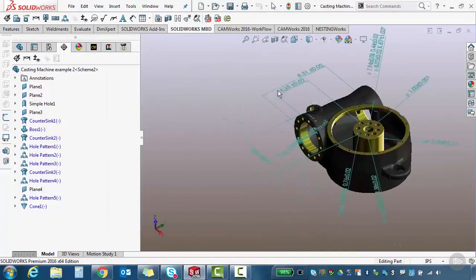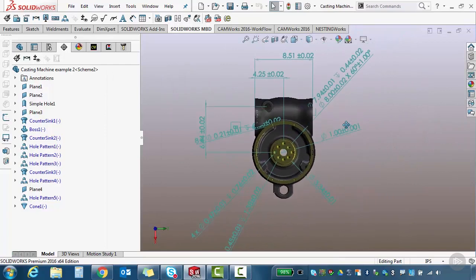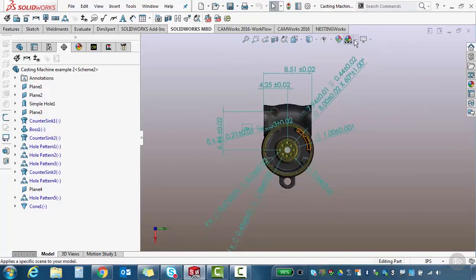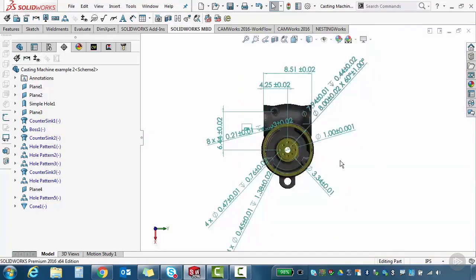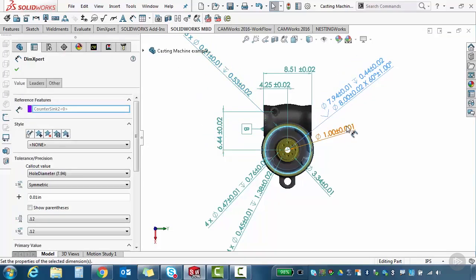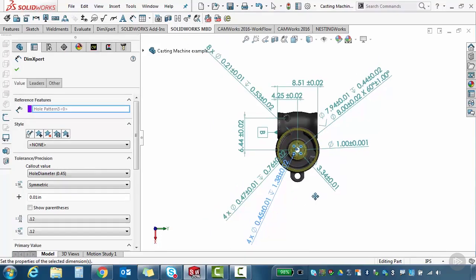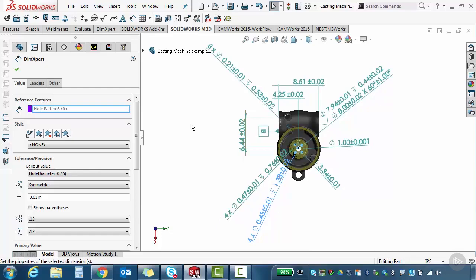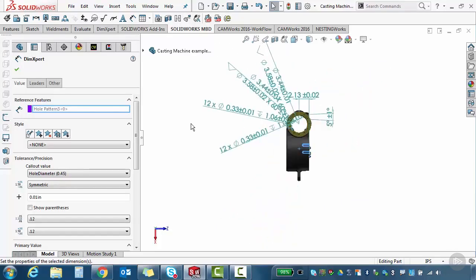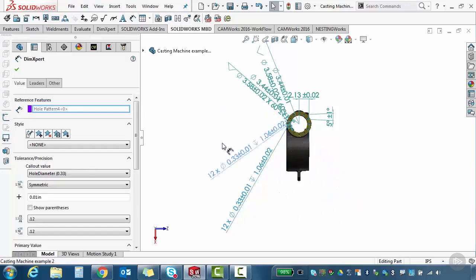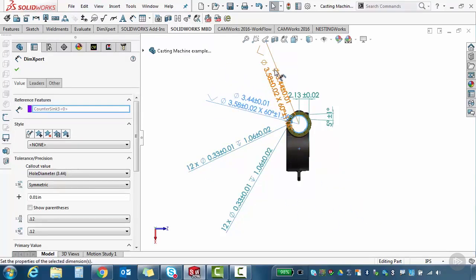And then if I look at this view from a plan view, and let's say we change this to a white background, you can see that all of these holes and all of this information has tolerances applied to them. Versus putting it in a traditional 2D drawing and then having to look between the drawing and the model, we have the ability to put all of that on our screen. And as I move from view to view, you can see I have different tolerances for different bits of information depending upon whether it's inside a hole, outside a hole.